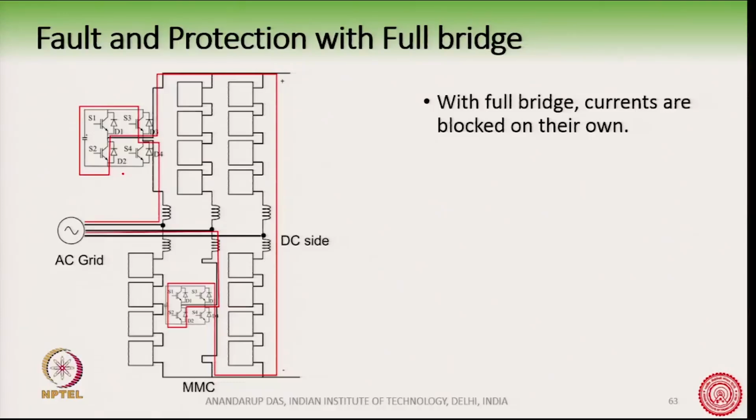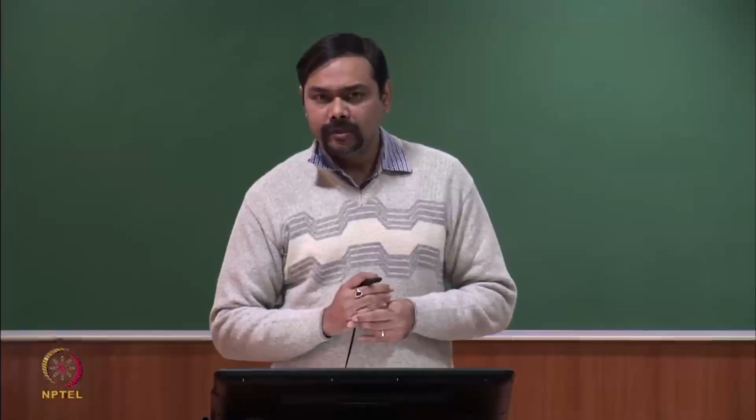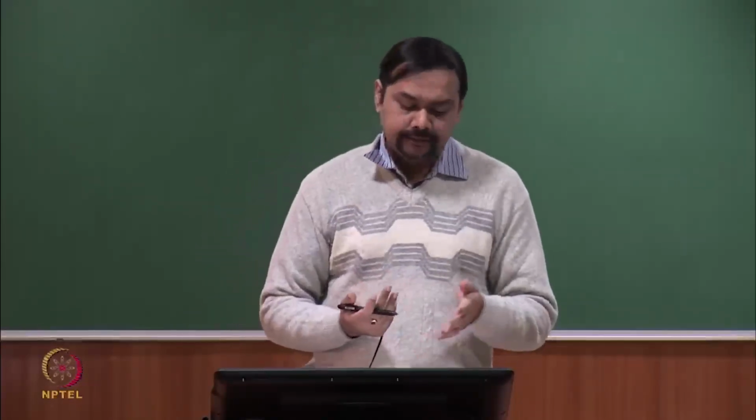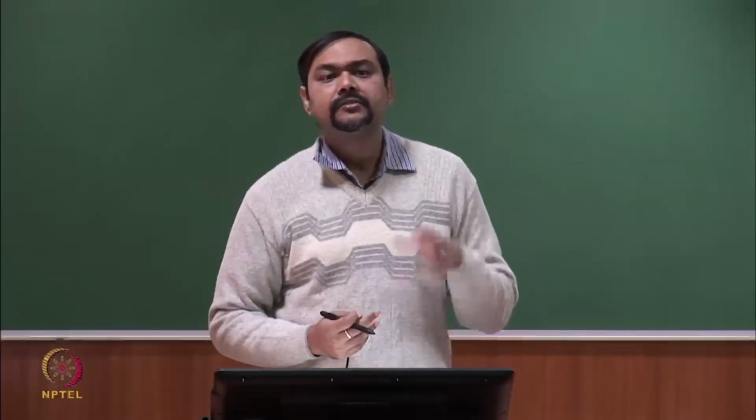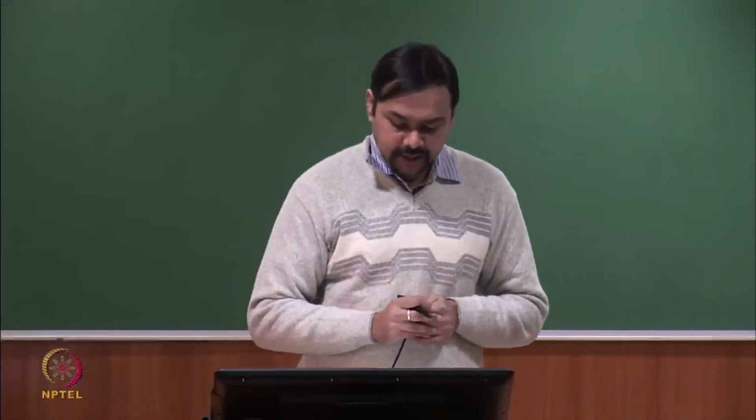A full bridge MMC circuit has a better performance than a half bridge MMC circuit during fault condition. So, many of the commercially established MMC use full bridge instead of half bridge. Okay. Now, of course, in a full bridge circuit, as you can understand, the losses will be more, because instead of using 2 transistors we are now using 4 transistors. The losses will be more, but the fault performance is much better in a full bridge circuit.